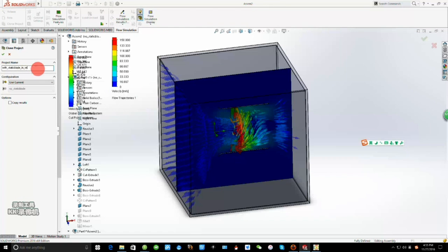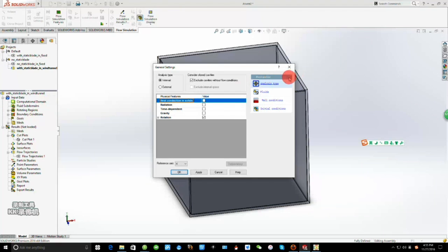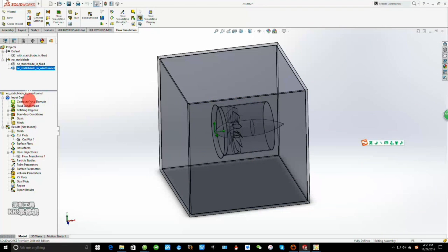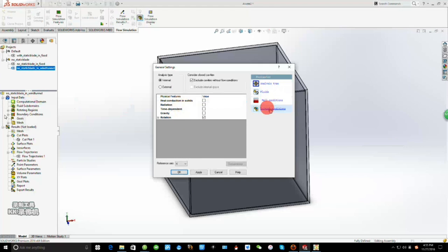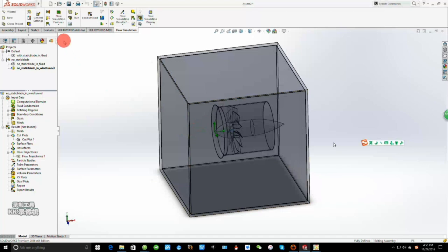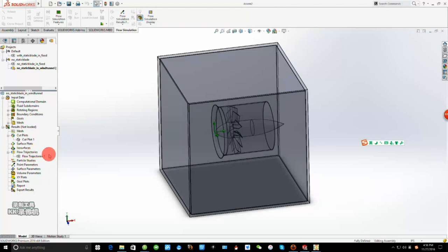Now, we have that. We're going to be doing it with a wind tunnel now. So what happens here is we go over to our properties, change the name, no static blade fixed. We now have the two configurations set up. Now, we have this facing in the X direction, so we're adding 20 meters per second, that's about 72 kilometers per hour wind, just hitting it, or I can't remember, I think it's traveling into it or traveling against it. It's one direction in the X.